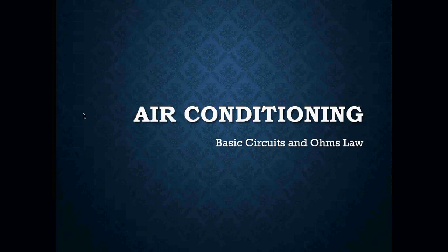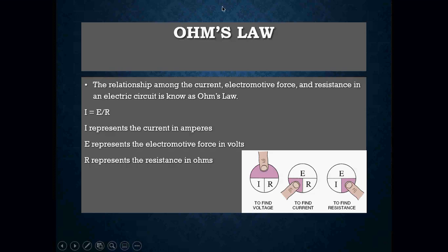Okay, so for today, what we're going to get into is some more basic electrical circuitry and some Ohm's Law. Now, with Ohm's Law, it's a theory that breaks down how your voltage, your amperage, and your resistance in an electrical circuit work together so that we can use electricity in a useful way.